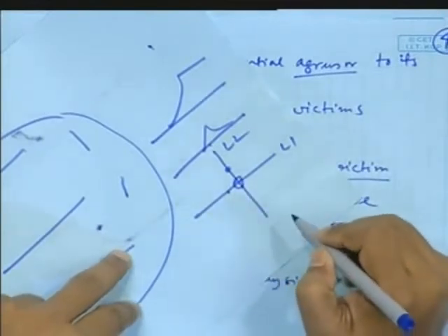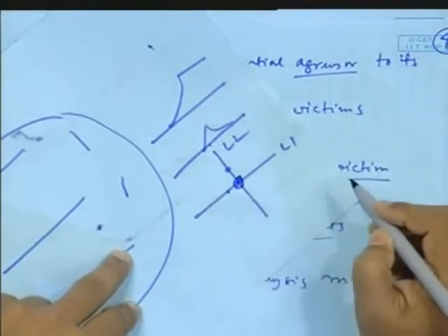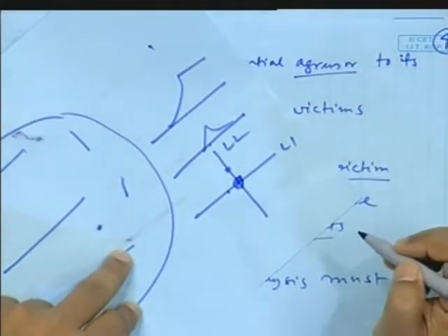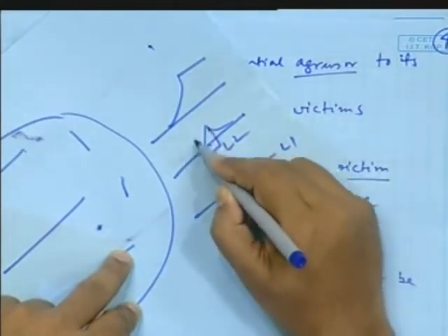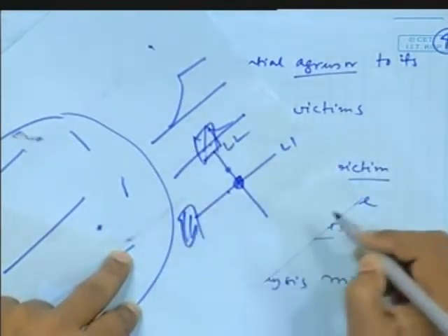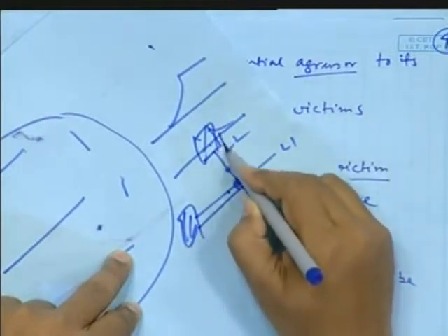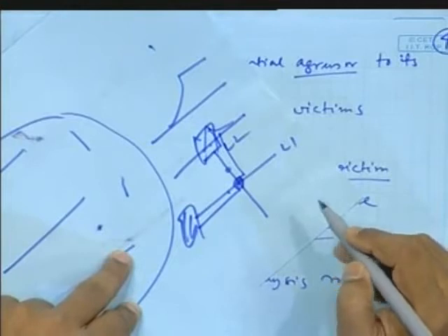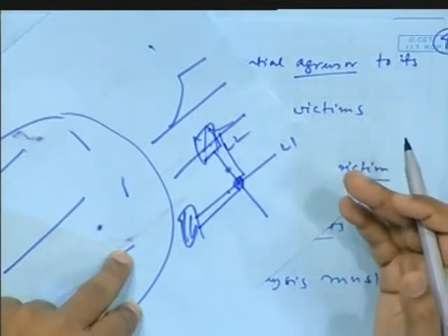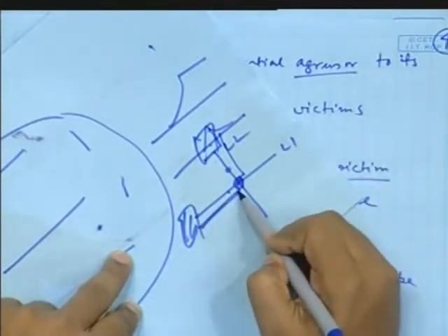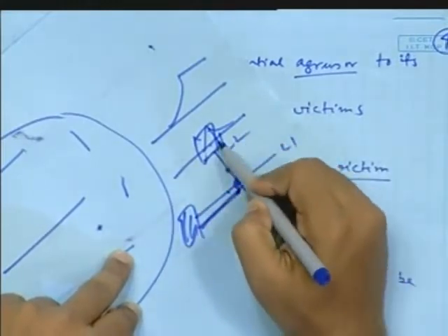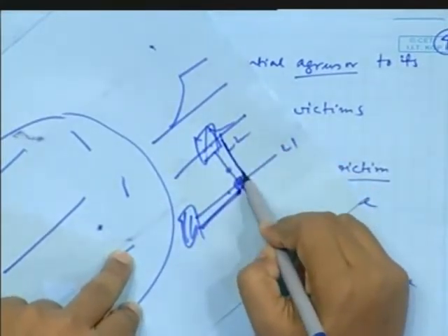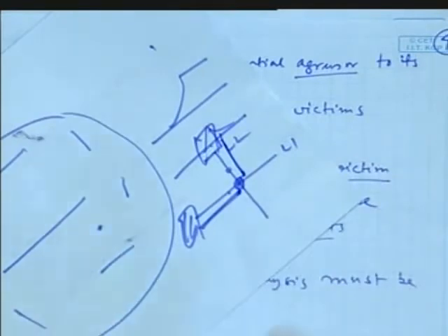This node, right? So I'll show you, there is a concept called timing window. Say this guy is being driven by some other fellow, and this guy is driven by some other fellow. If the time to this point and the time to this point are the same, crosstalk does affect, right? When this is reaching this point, when this is also reaching this point, there is a clash. It will affect, and then it will go.